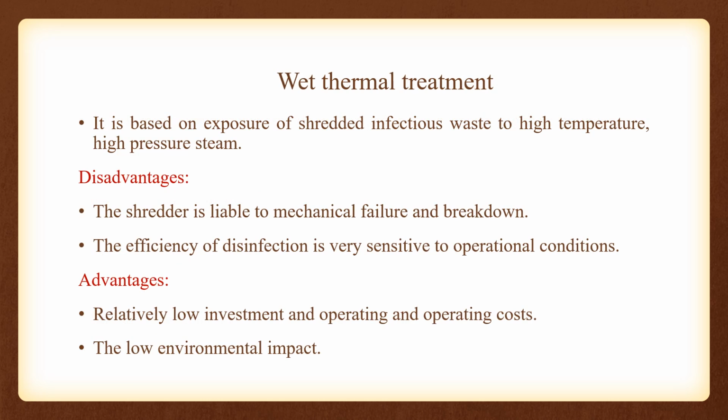And the third one of the disposal of healthcare waste is wet thermal treatment. Wet thermal treatment or steam disinfection is based on the exposure of shredded infectious waste to high temperature, high pressure steam. It inactivates most types of microorganisms. This process requires the waste to be shredded before the treatment to increase the disinfection efficiency. The process is inappropriate for the treatment of anatomical waste and animal carcasses.